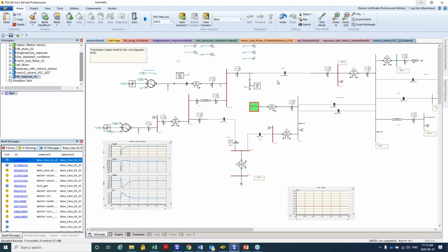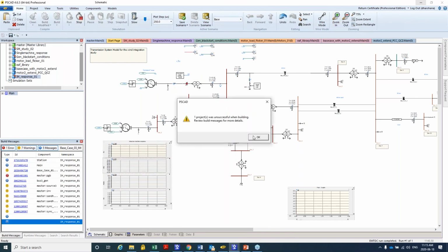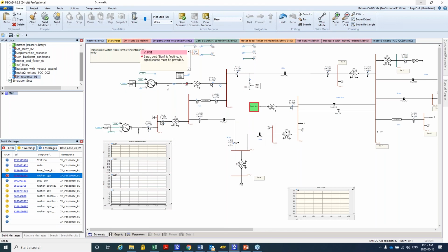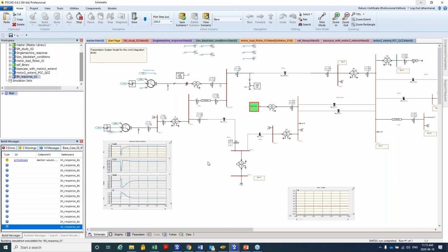So in this example, there is a fault in the system. Just to keep things simple, I self-cleared the fault. When you get this case, maybe you can clear the fault by opening breakers here at the 2 ends of the line. But what I wanted to show you is the delayed voltage recovery. See, the increased reactive power consumption of the two machines, and delayed voltage recovery.